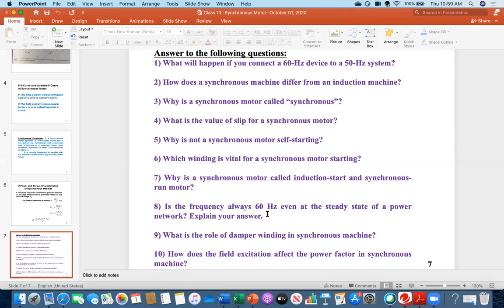I am using the load now; you may not use load at that time. So different customers have different patterns. All are not the same, not simultaneous. That's why there is continuously some sort of load change, either someone is injecting or someone is taking out the load. That impact goes on the generator, and consequently the generator impacts the frequency.